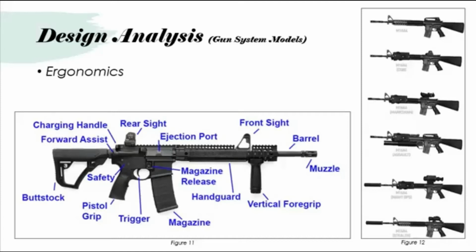Another phenomenon we must consider is the muzzle climb, which refers to a weapon's tendency to increase its muzzle elevation caused by compounded recoils following successive firing. This decreases weapon accuracy. Muzzle climb can be reduced by leveraging the operator's strength and additional weapon attachments. The pistol grip is angled toward the operator so that their hand's normal force is directed toward the ground, which redirects the muzzle back to its initial firing position.